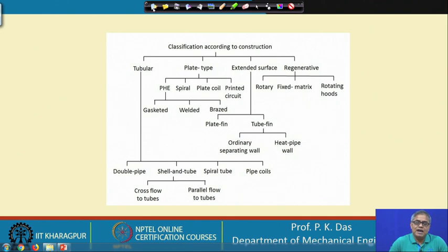Tubular geometry can withstand higher pressure, that is one advantage, and generally when liquid flow is there, there could be high pressure, and tubular geometry also gives very good sealing. So, sealing is not a problem, liquid leakage will not be a problem. That is why tubular geometry is preferred when there are two liquids.